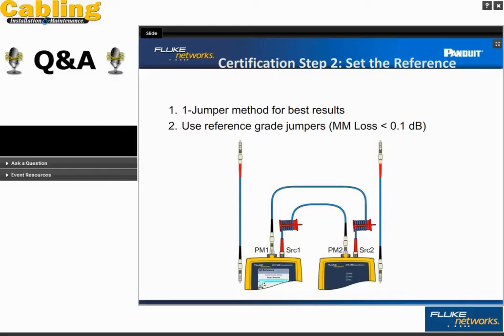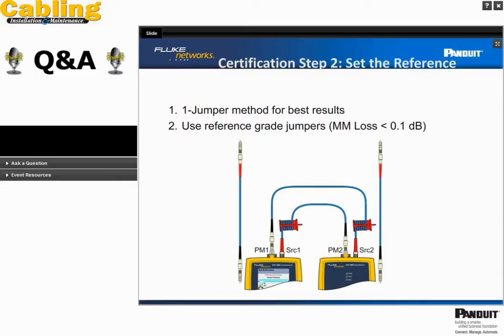It turns out that in very short reference tests, you will get light in a multi-mode system. You'll get light that travels in the cladding or outer parts of the core of a fiber. So you use this mandrel to strip those modes of light away, because they would absorb or disappear as soon as you plug it into a fiber of normal length that you're going to test.